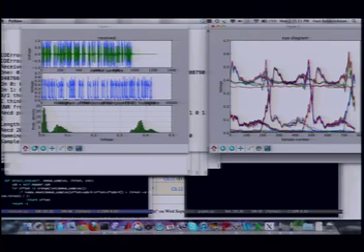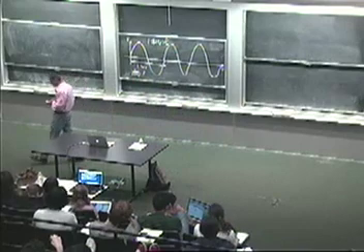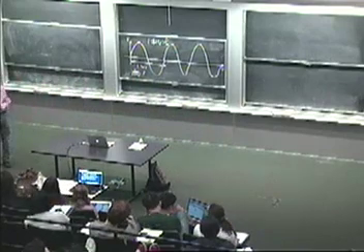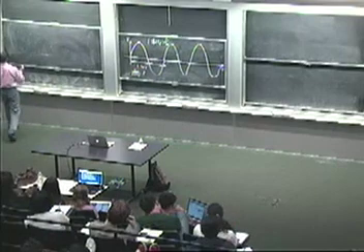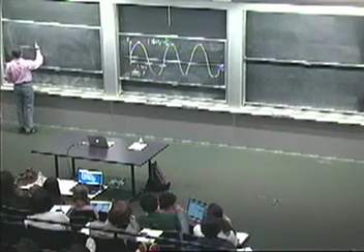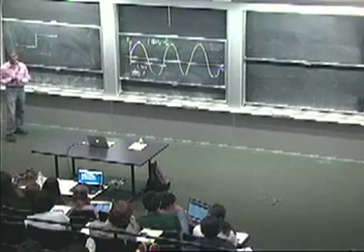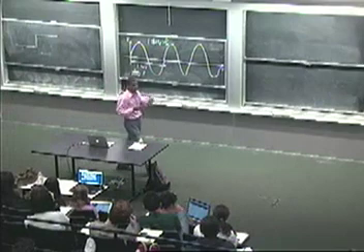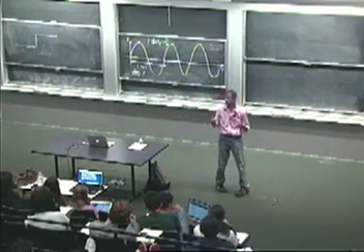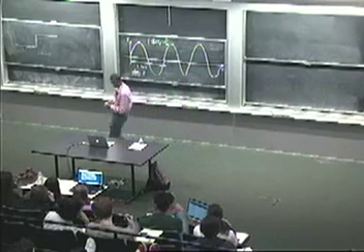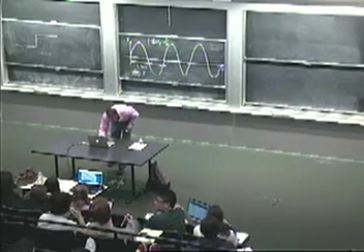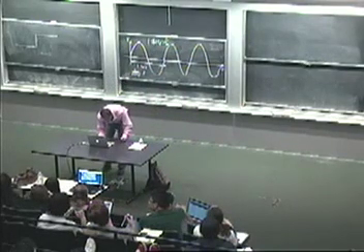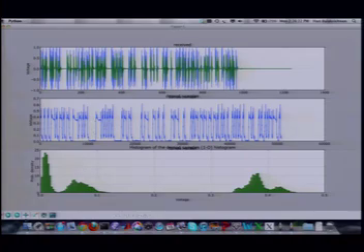The second is this thing that we've been studying by modeling it as a linear time invariant system. The idea is that when you have a sequence of zeros on the input and then you go into a sequence of 1 samples, that sudden sharp input transition does not immediately get captured at the receiver. It takes time for the 0 to settle into a 1 and a 1 to settle into a 0. And you can see that in this picture here. Now let's focus in this picture and look carefully at this place here.